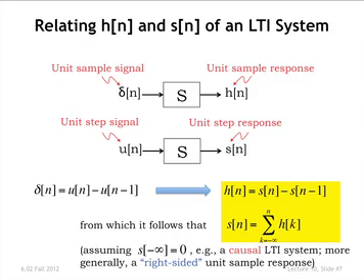But at some point, I need an actual value so that I can close off that expression. And if you're talking about a causal linear system, because the all zeros input produces the all zero output, and it's causal, you can actually deduce that the step response at time minus infinity must be 0. The input hasn't yet arrived, therefore the output must be 0.